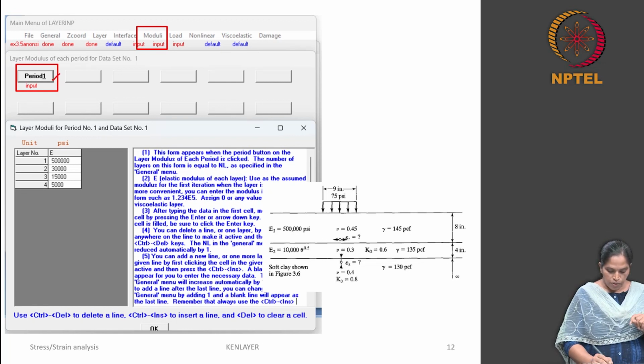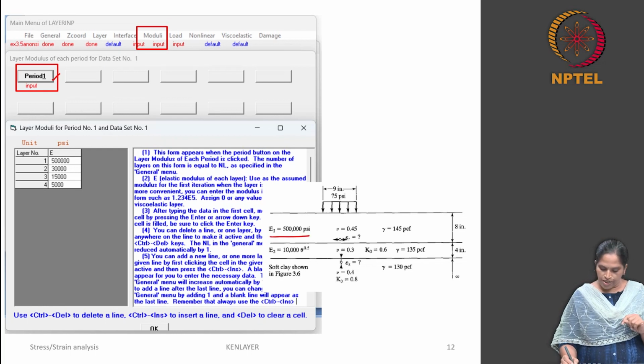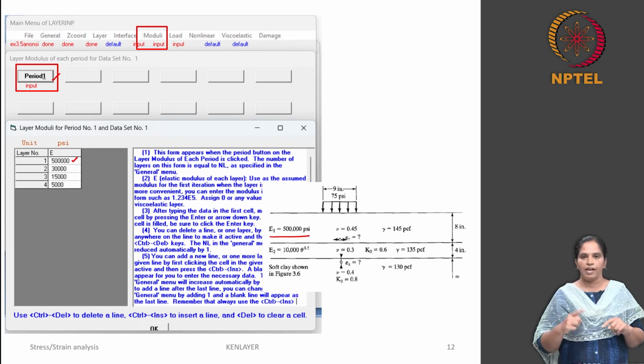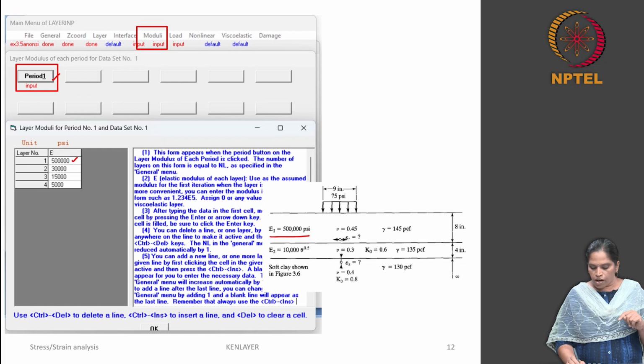Now if you see the modulus value, we used modulus E1 to be the modulus given for the asphalt layer. This asphalt layer is going to be an elastic layer with the same elastic modulus, and it is only one value. Now if you consider the base course, this is a resilient modulus value and it is a stress dependent resilient modulus, defined by this equation here.